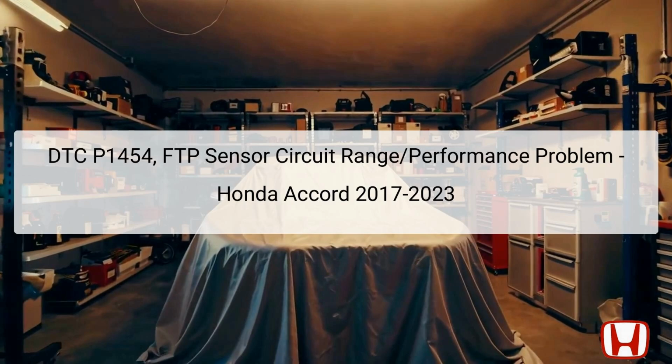The diagnostic trouble code DTC P1454 indicates there is a range or performance problem with the fuel tank pressure (FTP) sensor in the EVAP, evaporative emission control system, essential for monitoring fuel vapor emissions. The affected components are the FTP sensor, located near the fuel tank, and the EVAP canister vent shut valve, which controls vapor release from the EVAP canister. A malfunction in these components can lead to increased emissions, resulting in a failed emissions test.